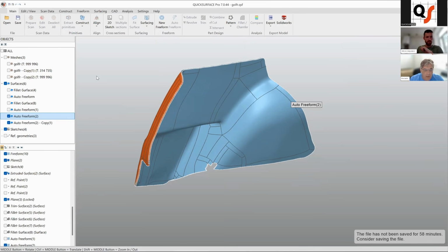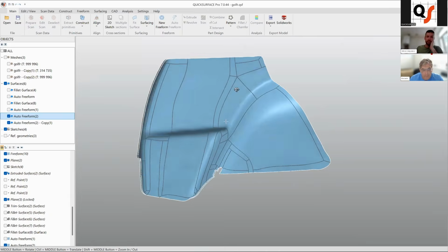For the offset surface, you may need to go and smooth a little bit and improve it so you avoid the self-intersections. But it just gives you this freedom to offset virtually every type of surface that you can modify later and achieve some results.